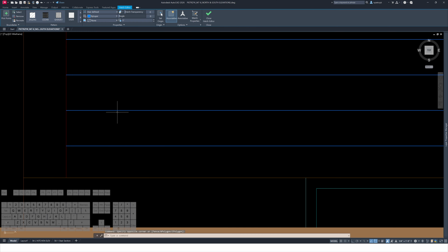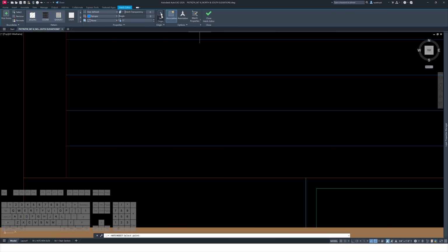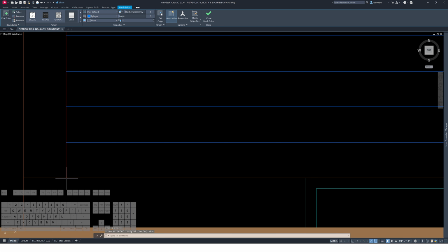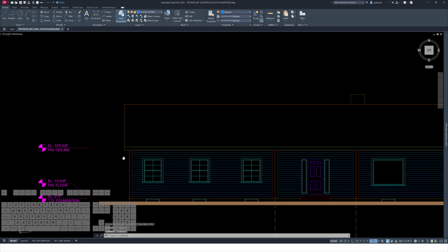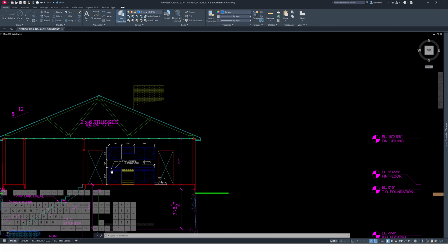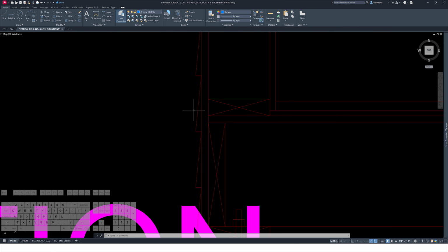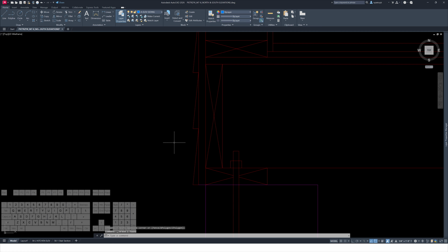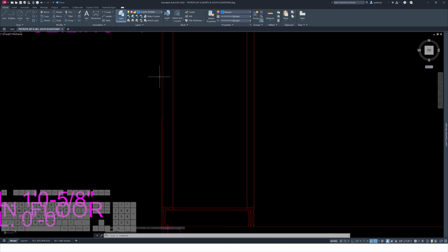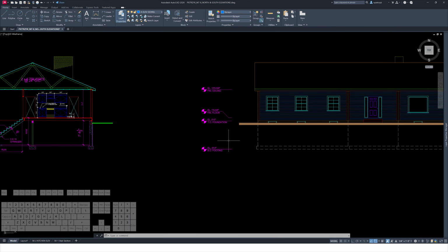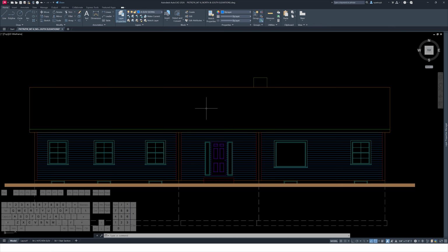So how do you fix that? I'm going to grab my hatch again, and I'm going to change set origin and click on the very bottom left. And you can see it scoots up. It doesn't matter the top isn't there. That is what we need. Because if we're recalling from earlier, it's in the way, our siding, we start our course in the very bottom and we work our way up. That's just how something like this gets built.